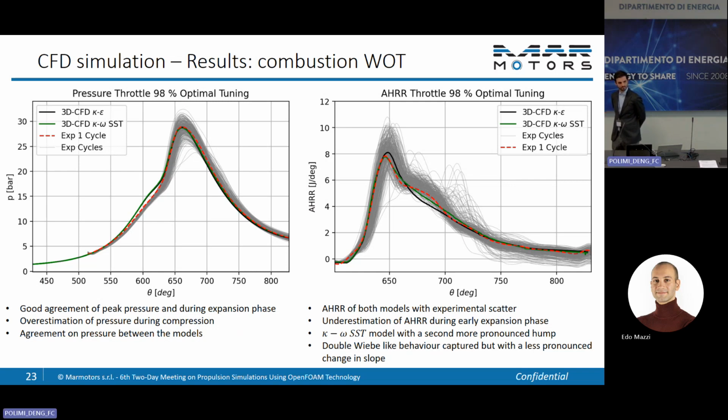Yeah, we share the same experience. I guess all these basic turbulence models and combustion models that were taken for granted, many of these IC engine simulations need to be revisited. But here I think it's more the flow and flame rather than the combustion model itself. When you get a good wrinkle factor, it propagates the flame, or it doesn't propagate. More attention to the flow features is most important.